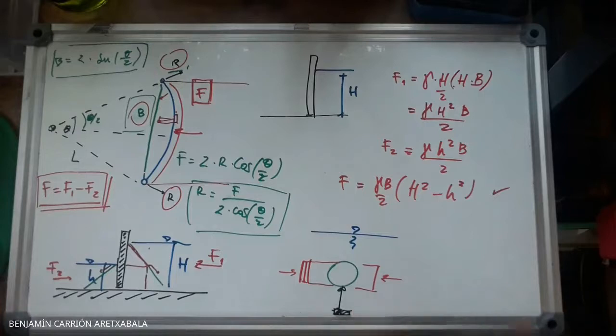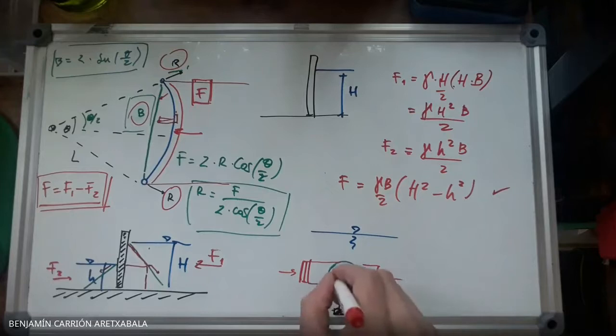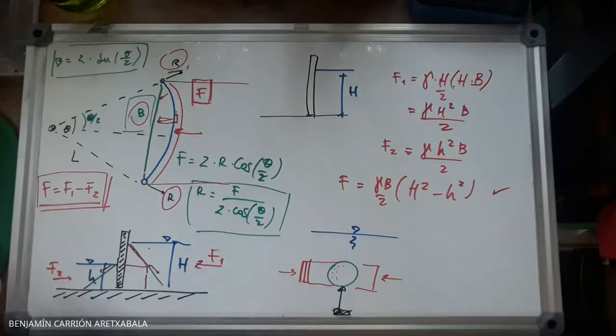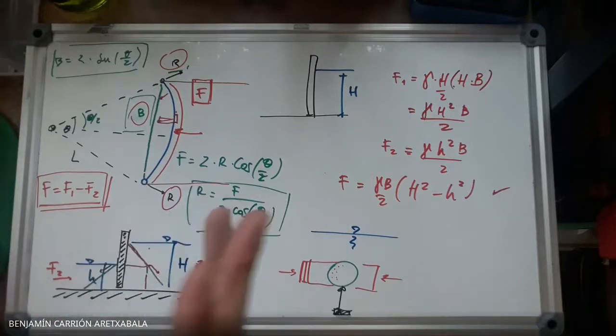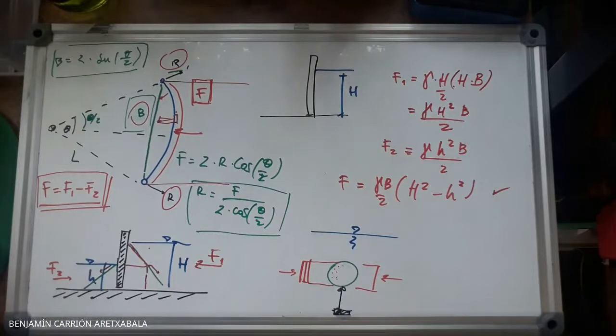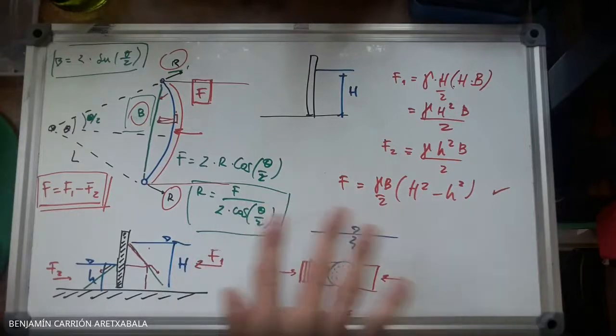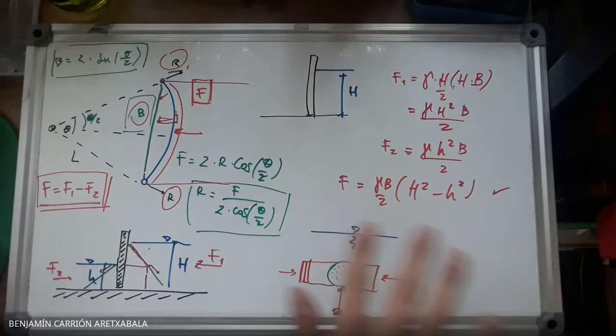But the lateral force only depends on the projected area. You could compute the force on each individual point on the sphere. But when you do that, and this was also the trick in the homework, once you compute the force on a small infinitesimal area, you have to decompose that force into its three components. So you're going to have two components on the horizontal and one on the vertical.